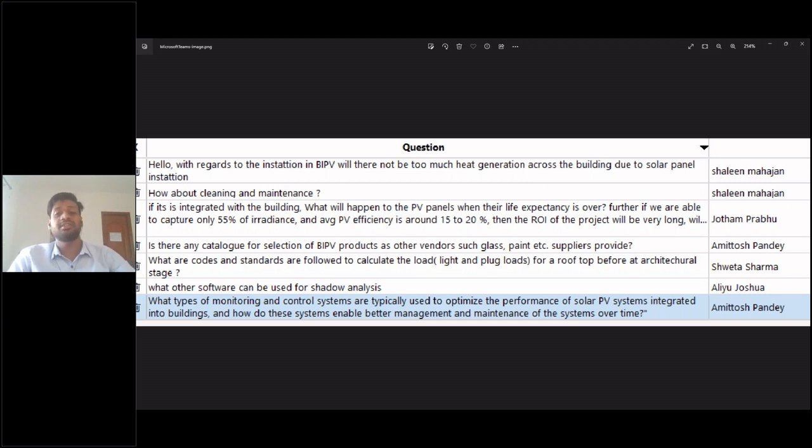It will be lesser than with the facade structure actually, because normal facade glasses will be transparent or translucent in nature, and they will let most of the heat pass through. But in the case of a PV module, we are capturing this irradiation which is available, and which will in turn act as a cooling effect. But we can optimize this based on your requirement, as in cases where it's a cold region and we need an inverse effect. There are PV modules available where a heating effect can also be achieved with the same technology.